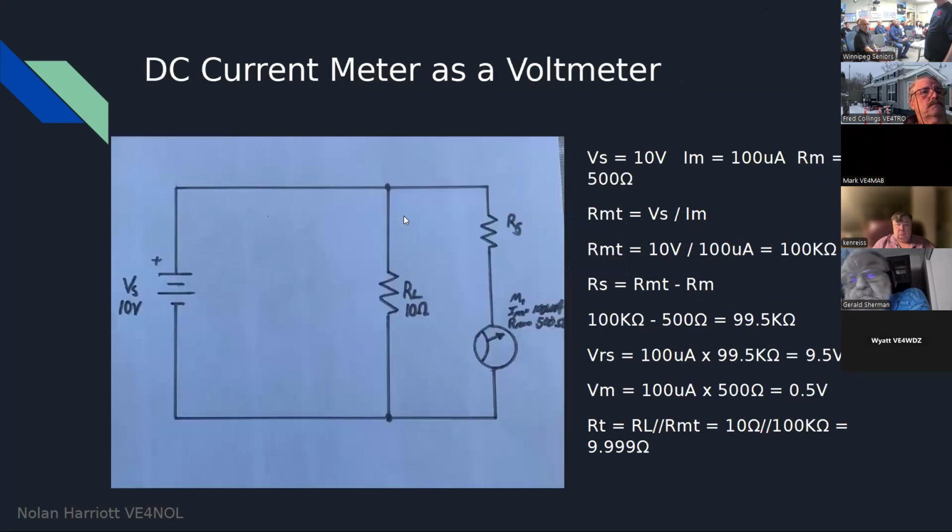So we see the same thing on a voltmeter. We now have two series resistors that add together, and they are in parallel with our load resistor. So this is no longer a total resistance of 10 ohms. It's actually going to be the parallel of these two together. So we have, again, changed the resistance of our circuit by simply connecting our meter into it. So our meter does influence our circuit.